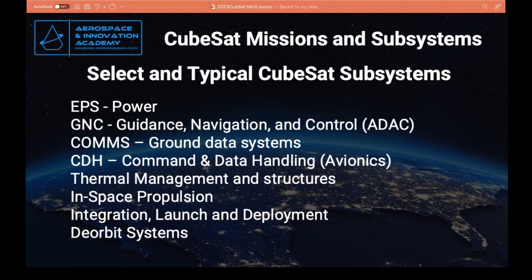And did you say those could be 3D printed? Some components can. It depends on where your satellite is going. If your satellite stays close to Earth and isn't producing a lot of heat, it's quite possible that you could have some plastic type components, but you're always careful about outgassing and the temperature range.